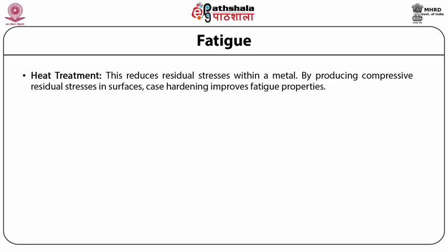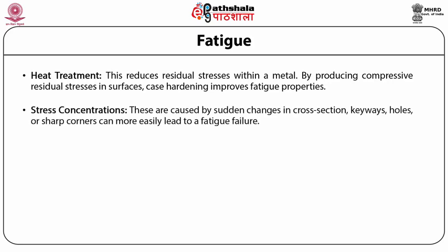The seventh factor is stress concentrations. These are caused by sudden changes in cross-section. Keyways, holes or sharp corners can more easily lead to a fatigue failure.